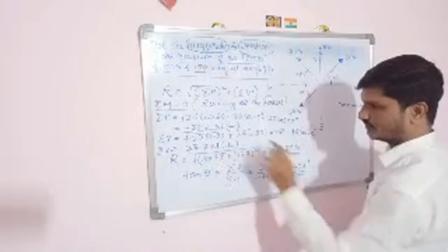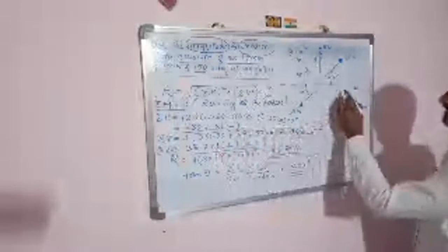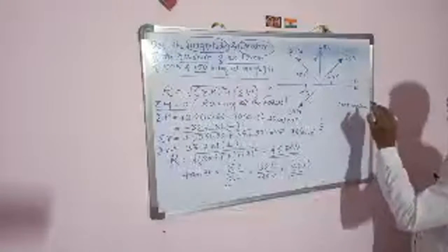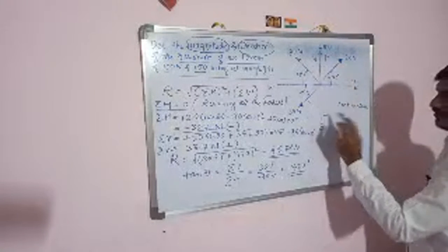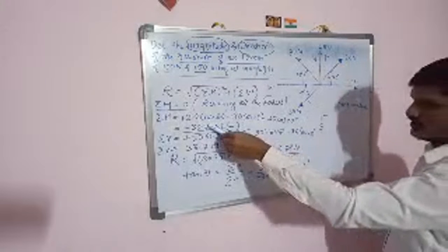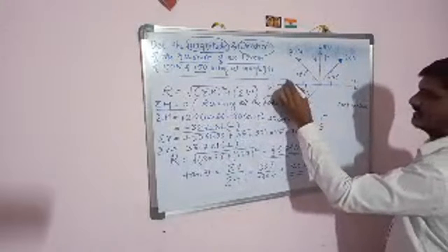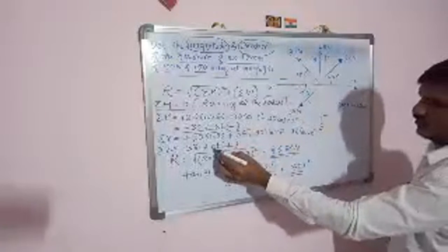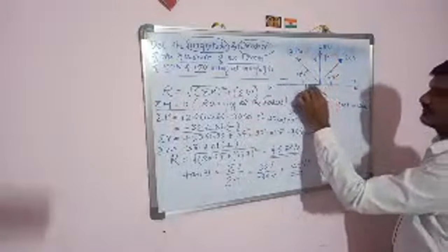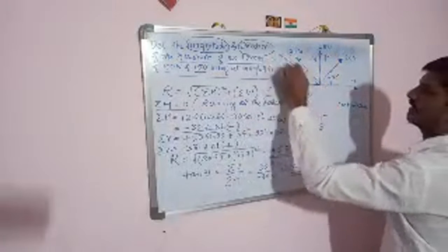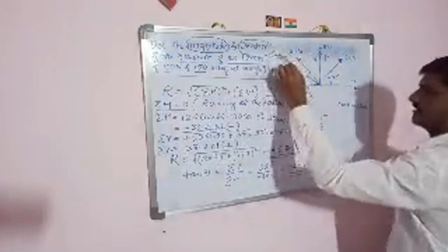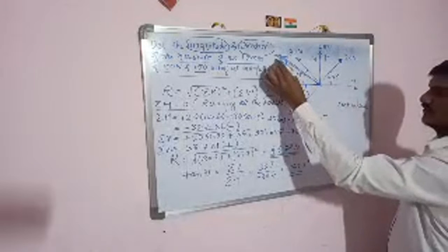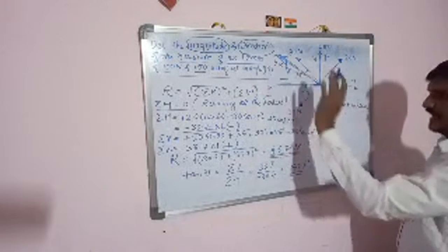force it is positive. So horizontal is negative, so horizontal negative is always on the left side, it will be right side in the positive, and upside positive, downward is negative. So now you got horizontal as negative, it means the resultant is somewhere in this quadrant, and vertical one is positive, it means the resultant force lies somewhere here. This is the resultant. R value is how much? 45.58 is acting at an angle of